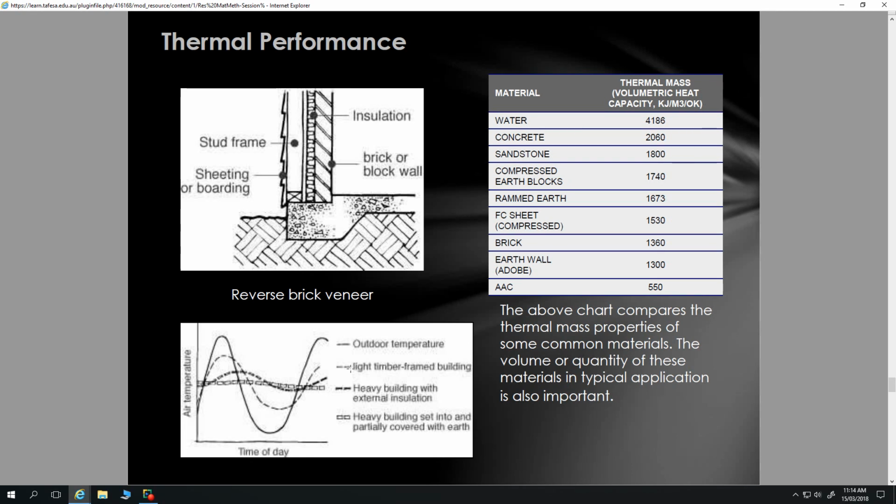On the outside of our building, that's where we have all of our thermal mass. Well, we've got thermal mass in the slab. That's fantastic. A lot of that thermal mass is inside. But a great portion of the thermal mass is in the brickwork, which is on the outside. And then we have our insulation in here. We're not really making use of that thermal mass properly.